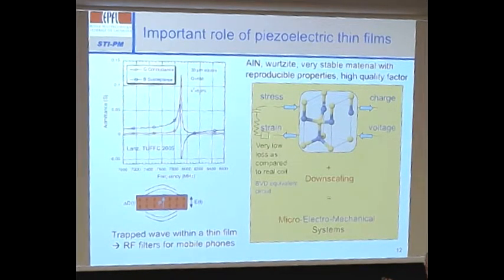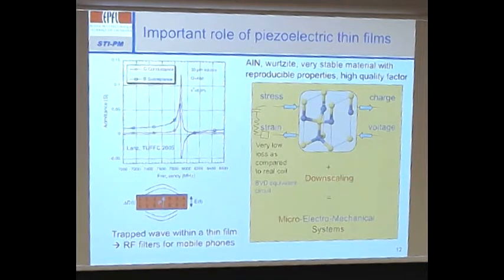That's in electronics. It can be used as substrate because aluminum nitride is a relatively good heat conductor. You know, alumina is not as good as aluminum nitride. And glass is a very bad heat conductor. So where they need better cooling of ceramic substrates, they can use aluminum nitride.